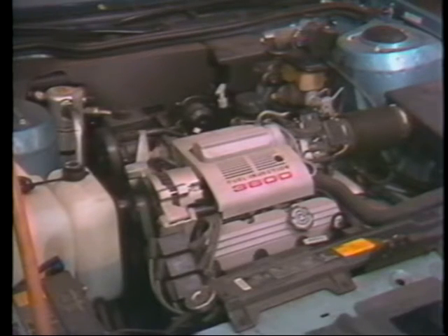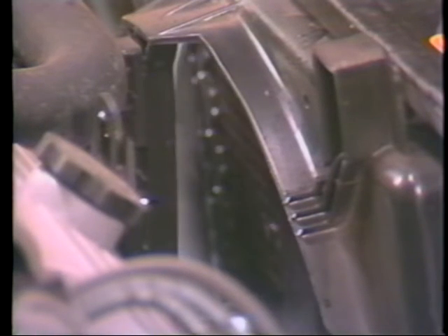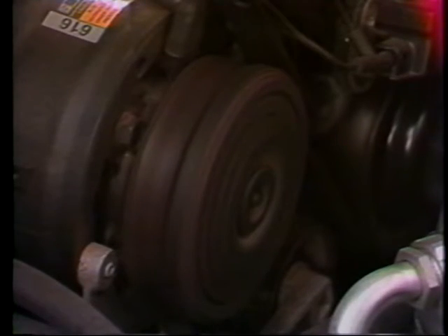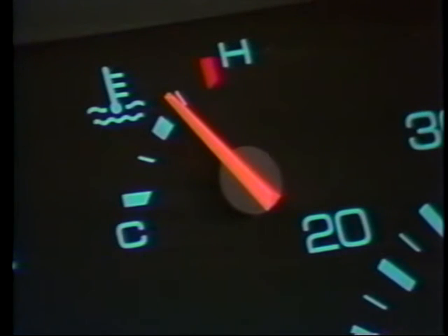While we're on the subject of cooling fans, front-wheel drive vehicles with transverse-mounted engines use an electric cooling fan. This fan provides an even greater increase in fuel mileage. In most cases, the fan does not run at all when the vehicle is moving unless the air conditioner's on. When the vehicle is sitting still, the fan will operate when coolant temperature exceeds a specified point.